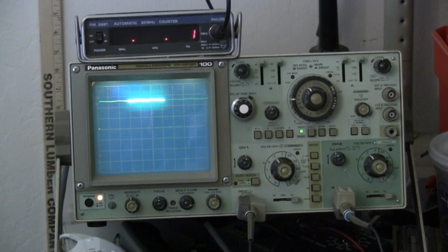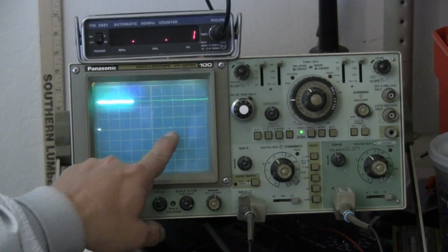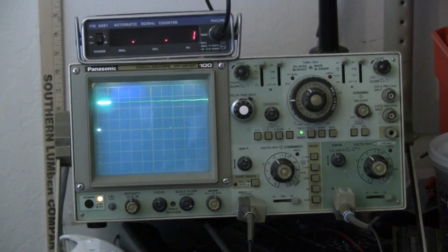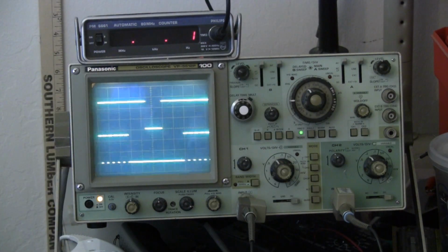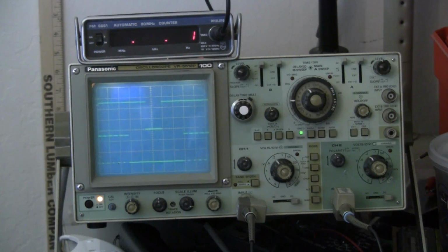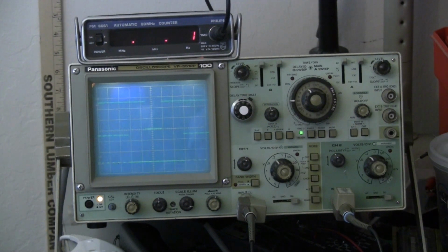Okay, we're now looking at the vertical sync pulse. This is occurring at a 1/15th of a second rate. From the first pulse to the second pulse is 667 milliseconds, or 1/15th of a second. And there we're looking at the pulse widened out. Now we compare it with composite blanking, and you can see the vertical blanking period, which is 11 lines wide. The vertical sync is on the upper trace, and the composite blanking is on the lower trace. And of course it's flashing vigorously because we're only getting updated 15 times a second, and we're looking at a very small portion of it, which has a short duty cycle, so it's going to flicker. This video format is going to be one epilepsy-inducing little monster.